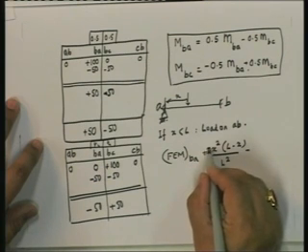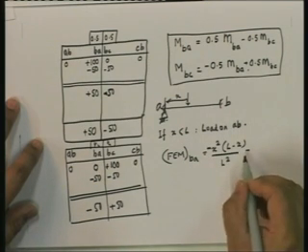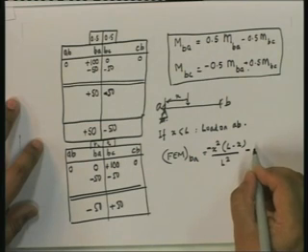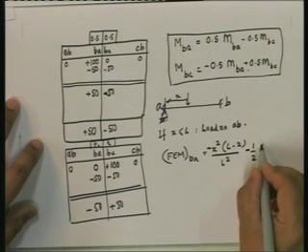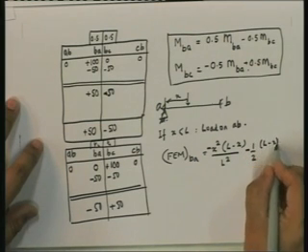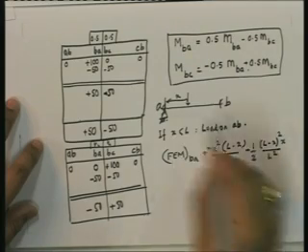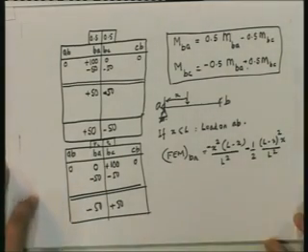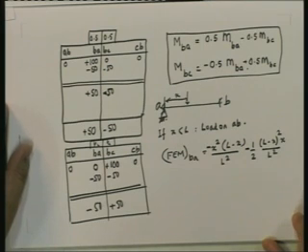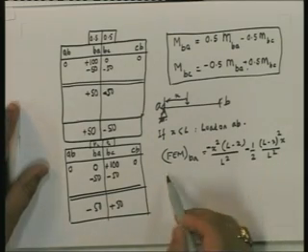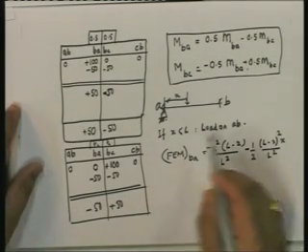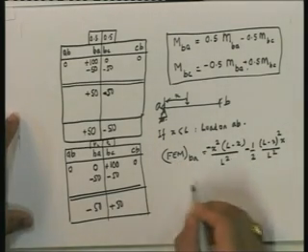Sorry, this is minus because it's anti-clockwise. This is also minus half (L minus x) squared x upon L squared. You do it. I have done enough of this to let you know how you can find this out directly. This is the fixed end moment if x is less than L.